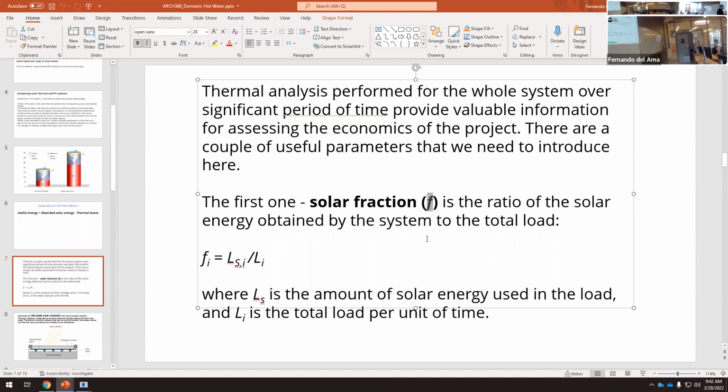We want energy, and we have these three factors: the amount of fluid or the flow of water, and we can increase the amount of water that we are running with this pipe. We can't do anything with this, and then we have to consider the difference between the inlet and the outlet temperature. So that's it. This is all we have to understand. And the only thing we can do, if we want a big gap between the inlet and the outlet, reduce the flow of water. If we want to reduce the gap between the inlet and the outlet temperature, increase the flow of water.